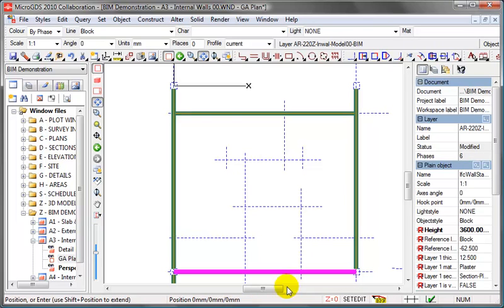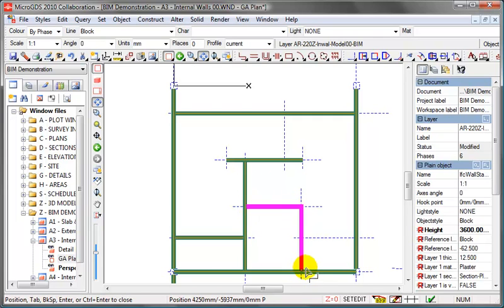That's the outer wall set, and it pays to think carefully about how you're going to lay out a complex set of walls like that. It's easier to position the walls between faces rather than lay the wall out and then have to adjust it later. It's down to your choice as to which is the workflow you prefer, but just a little bit of planning in how you place these walls means that you don't have to worry about editing so much.